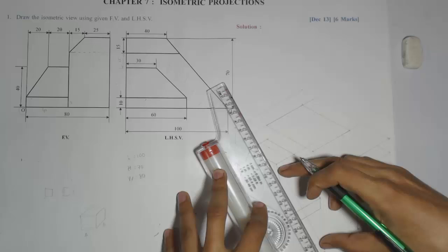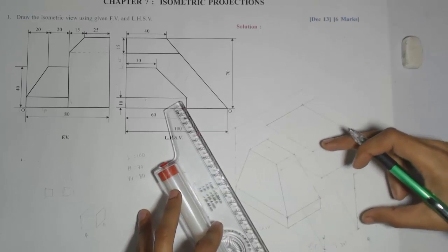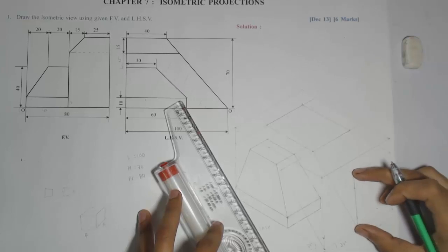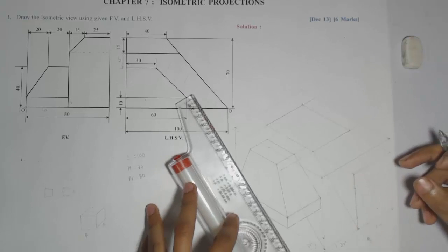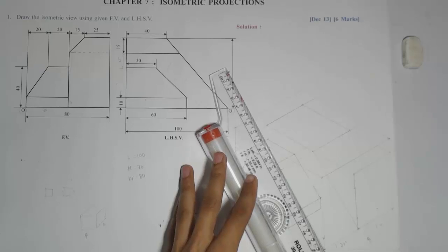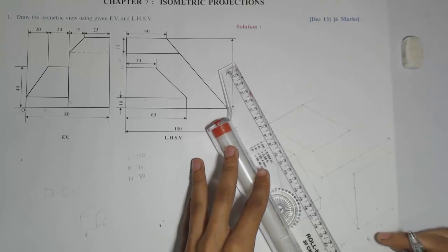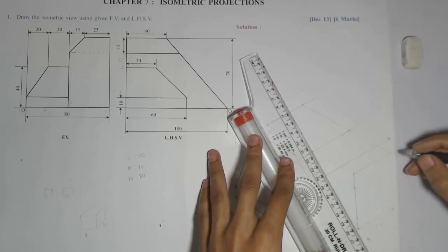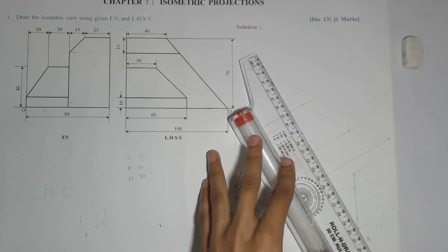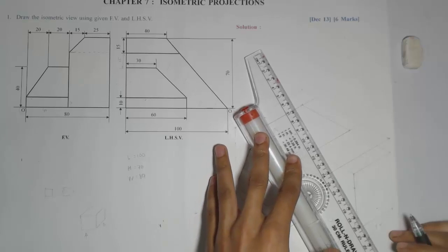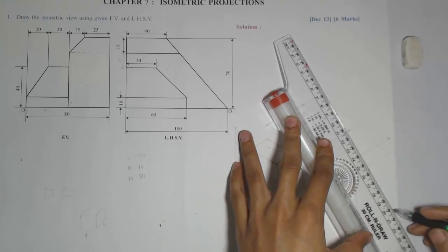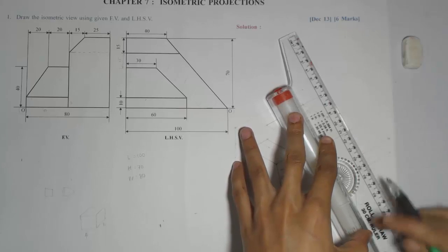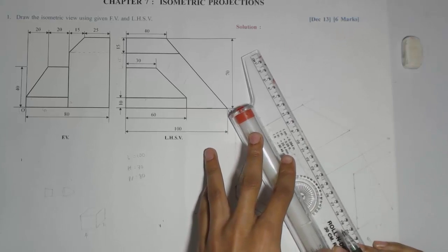Okay, this line in left hand side view is giving me the true length inside view, but corresponding front view is the apparent height, this one. Similarly, this will be redrawn again from the opposite corner also, because this height I am getting on this boundary also. So this will be repeated twice. So I need to draw one more parallel line from here. So we are getting two parallel lines.